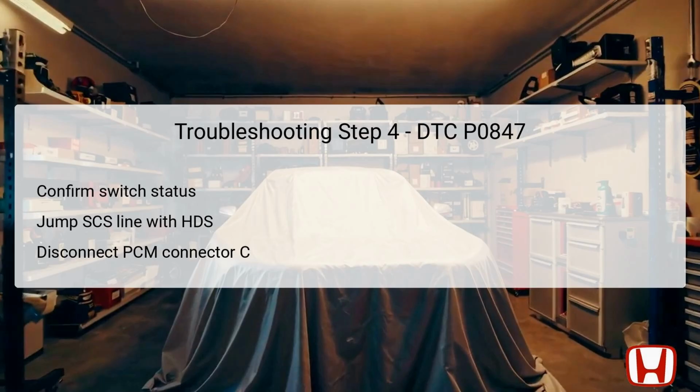the transmission operation. This step is vital as it allows you to evaluate potential communication errors or faults stemming from the PCM. Ensuring proper isolation and connection integrity will help to confirm whether the issue truly lies with the switch or within the PCM wiring and circuitry.